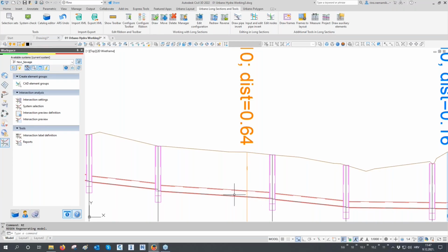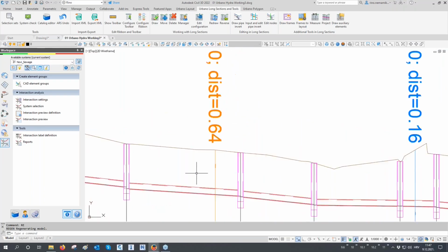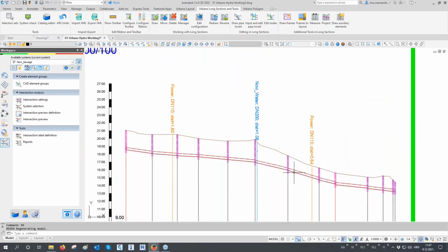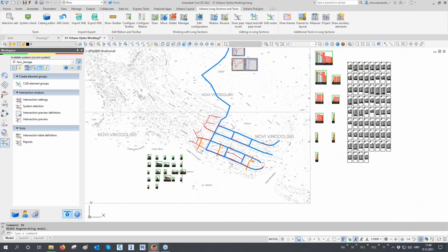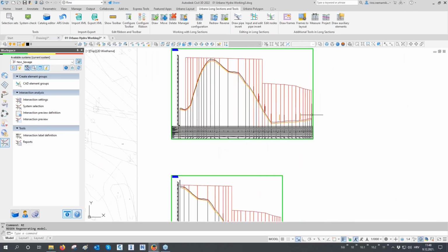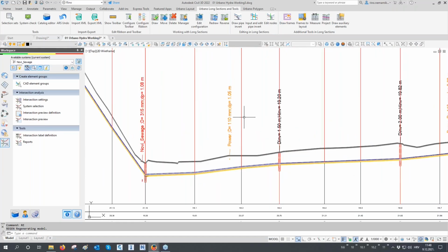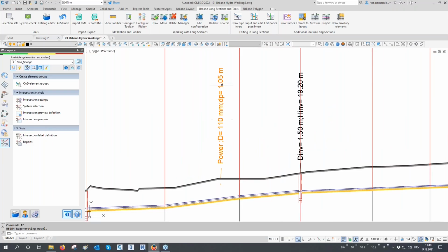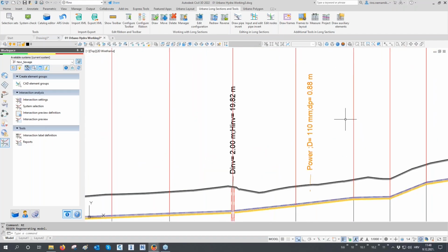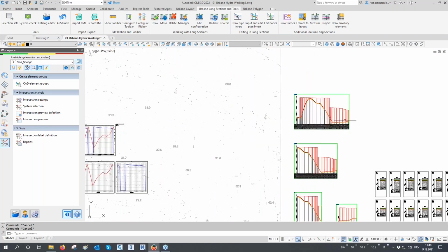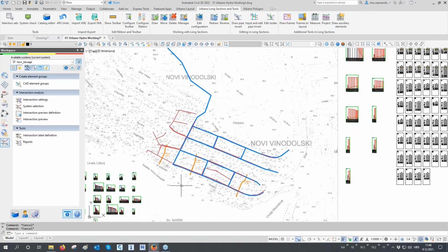So this was the original Urbano topology, and this is the CAD element groups, but it's treated like any other pipes in Urbano. So this is the sewage system. And let's also check our water system. Our water system, and here it is, the crossings between the power cables and our newly designed water distribution network. This can be a lot helpful and really great functionality if you have a very big amount of such polylines that you don't need to convert to Urbano systems.